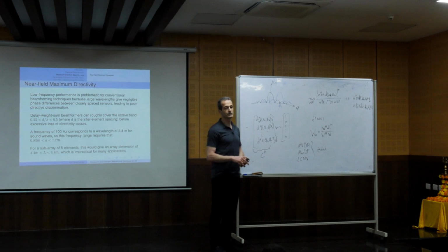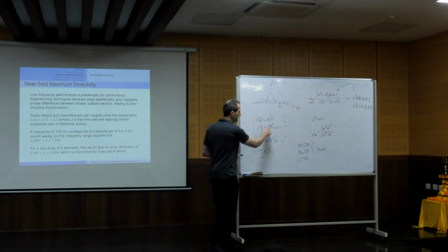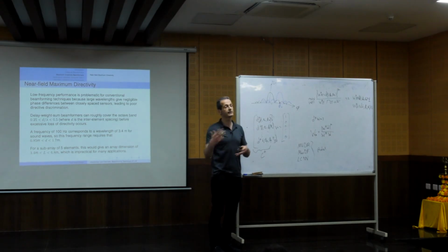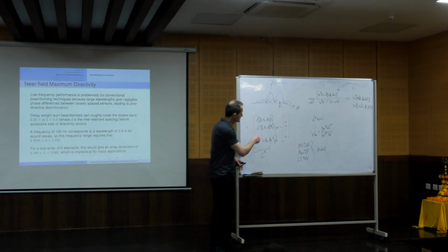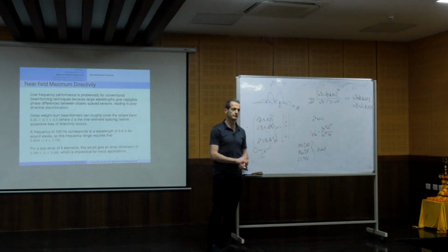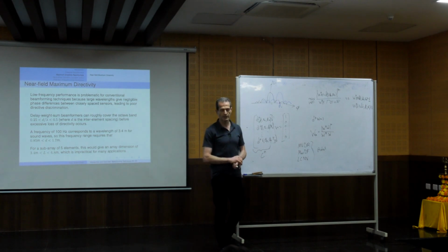Okay? So this is called region of interest beamforming. And if I have nulls in a certain region, I can call it region of non-interest beamforming. Okay? So I can solve it instead for a certain position of the source, for certain regions, certain areas of the desired source or undesired or non-interest sources where I want to put nulls.